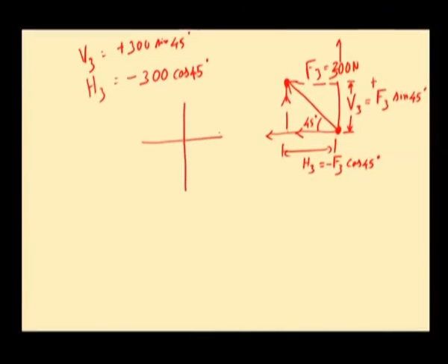And finally, we have one more force which is of magnitude 350 Newton. It is at an inclination of 40 degree from west. Now, we shall resolve this force along vertical and horizontal direction. So, this is the horizontal component H4 and this is the vertical component V4. So, the force F4 starts from the origin, that is origin is this point, and it ends up at the tip of the arrow mark. To travel from the origin to end up here, horizontally we have to move towards left and vertically we have to move in the downward direction.